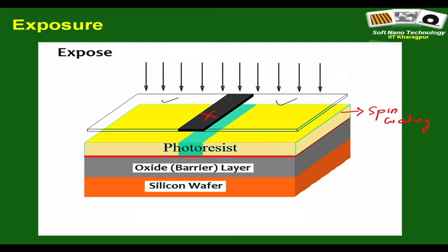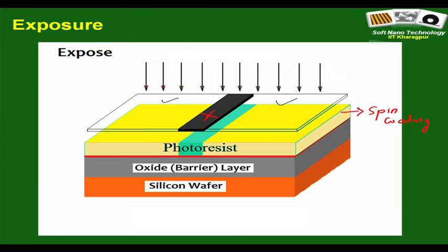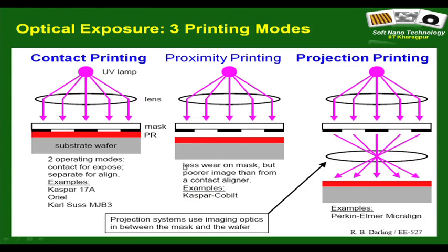You should understand this fully now. You should expect the photoresist to change its property, and now you cannot really comment from this picture whether, of course in a real process you will know whether you are using a negative photoresist or a positive photoresist, that is not the issue. But if I ask you from this schematic what has happened, all you can say is that upon exposure these yellow areas have changed property, which is expected, because looking at the geometry of the mask, those are the areas over which the UV light came in contact with the photoresist layer, and therefore, it has changed property.